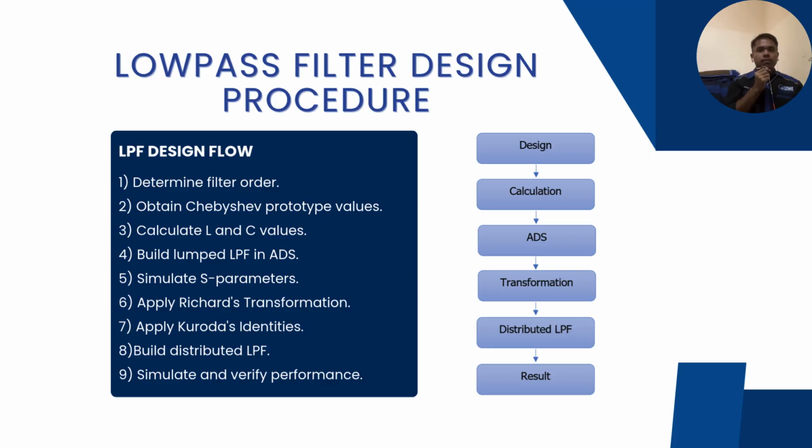After obtaining the lumped filter result, Richards transformation and Kuroda's identities were applied to convert the circuit into a distributed implementation. Finally, the distributed filter was simulated and verified to ensure that it met the required specification.